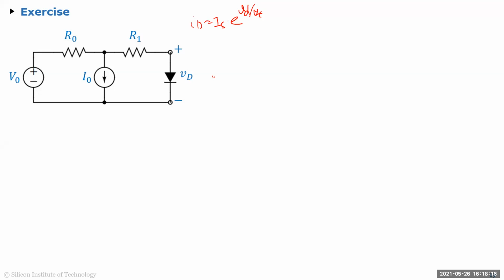So if there is a nonlinear device, you can't use node equation because KCL, KVL, node equations, Thevenin, all these are only for linear systems. You can't use nonlinear devices to solve it this way, because when you're applying superposition, the idea is that it is a linear system. If you have a nonlinear device there, then all bets are off. So you can't actually solve this. But someone asked a good question, like, okay, can I take it as 0.5?